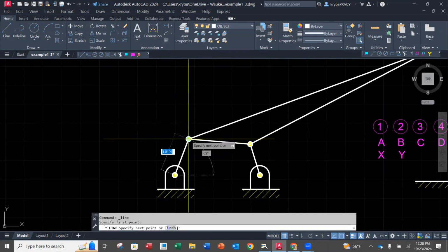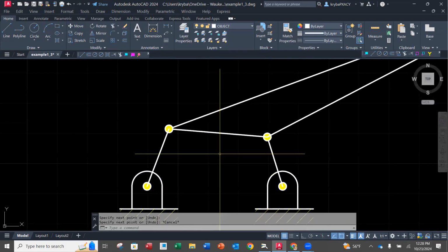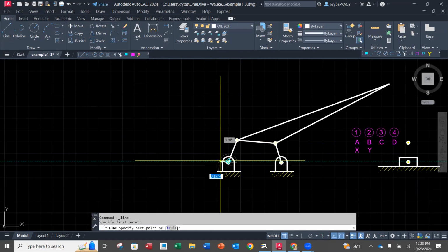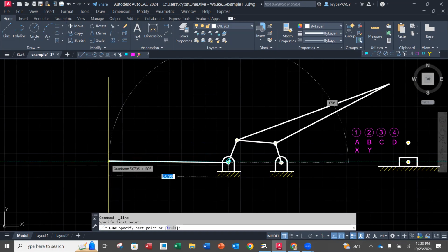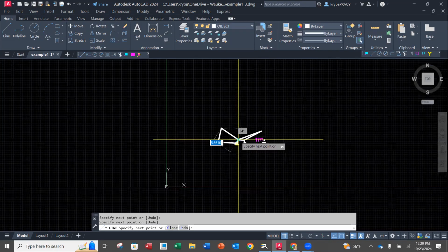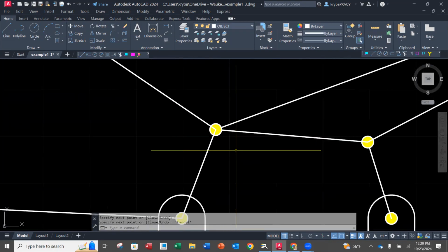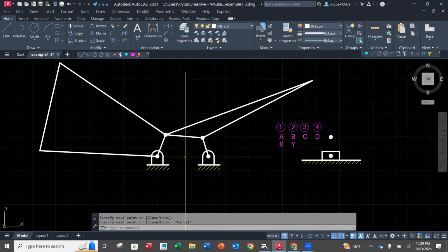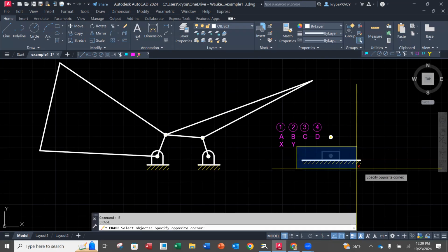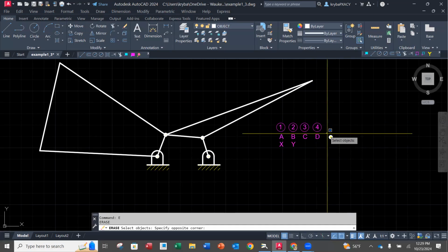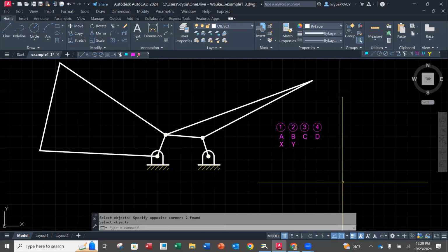Now I'm going to draw a line from the center here to the center there. And then I'm going to draw that front end of the clamping link. So I kind of put it here, here, and something like that. Okay. All right. So in this particular kinematic diagram, there is not a sliding element. So we can just erase that slider. And I'm also going to erase my joint, I'm now done with it.